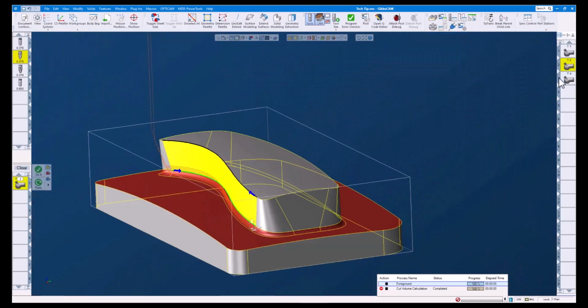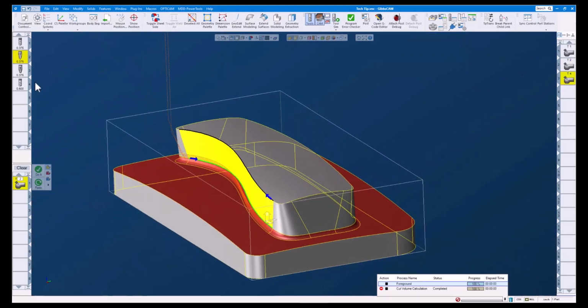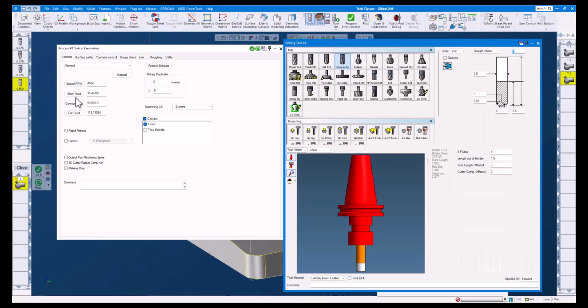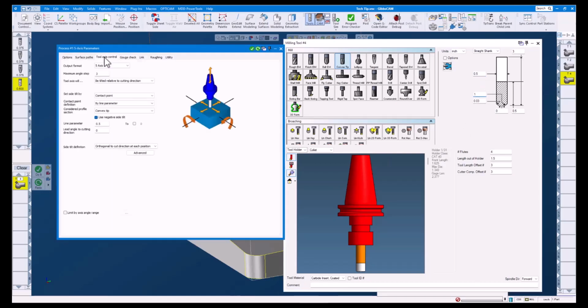For our last example, let's open up Operation 3 in Tool 4. This tool is called a convex tip, or sometimes referred to as a lens form tool. The tool is 1/2 inch diameter and has a 1 inch radius on the bottom, great for finishing floors. For our profile options, we have the convex tip selected and a line parameter of 0.5.